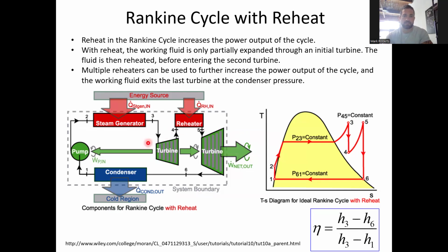So Rankine cycle, and again, there's various different configurations that these are done in, and all of it is to increase the amount of work that we can get out from the amount of heat that we put into the process. And Rankine cycle with reheat is, just looking at it on the TS diagram, again, we get our superheated steam. This is what enters the turbine.